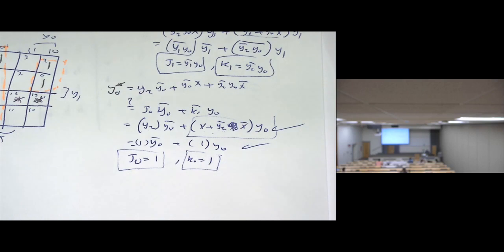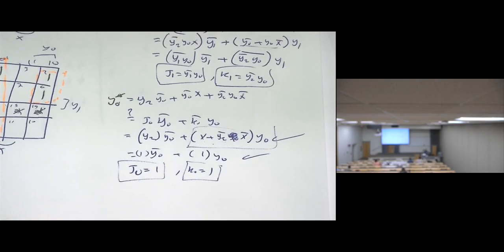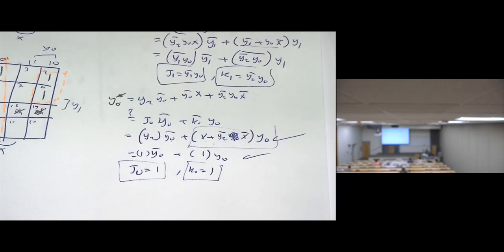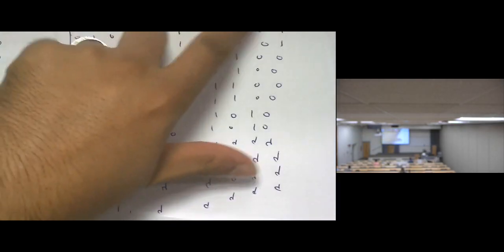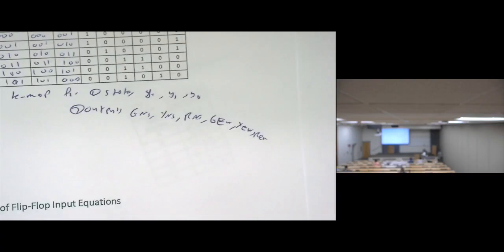Okay. Now we're done with the equations associated with the states. How about the outputs? How many outputs do we have? 1, 2, 3, 4, 5, 6. So we need to make 6 Karnaugh maps, 4 variables. Oh, it's going to be tough. But let's have a look. We can make a small shortcut. Let's look at the small table.